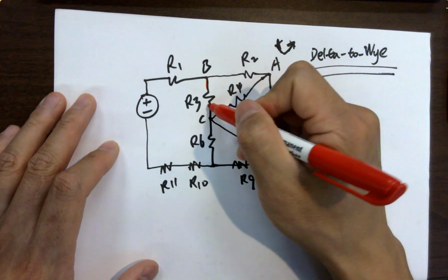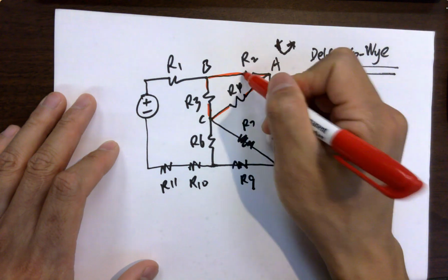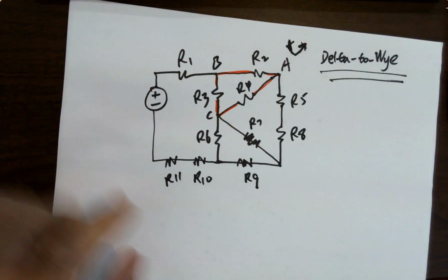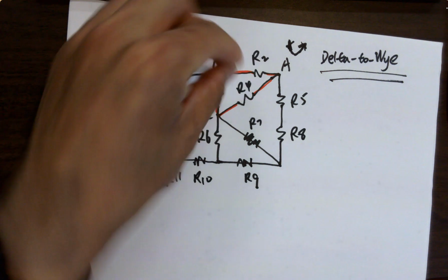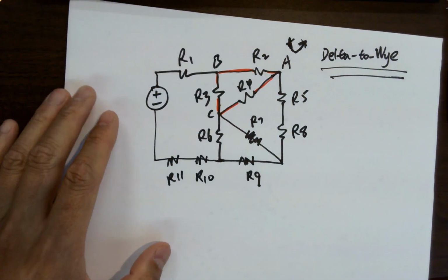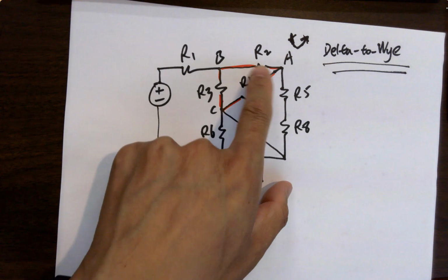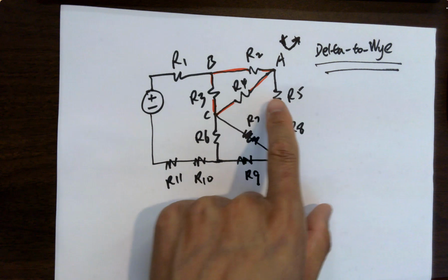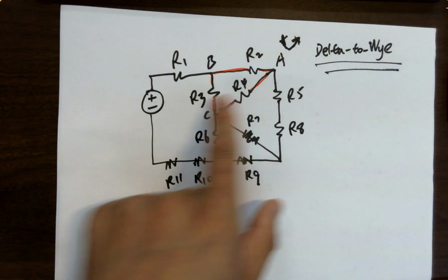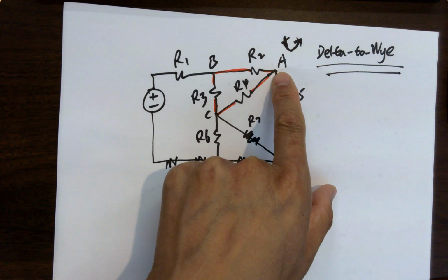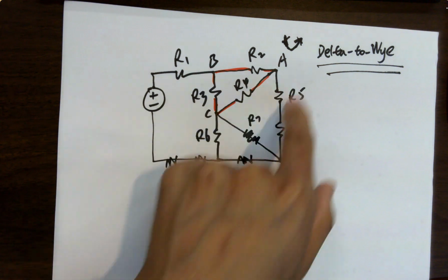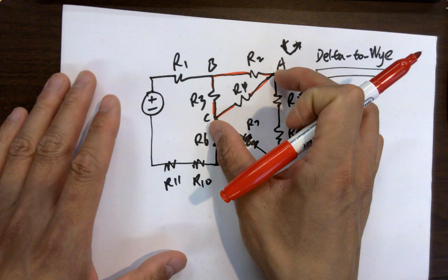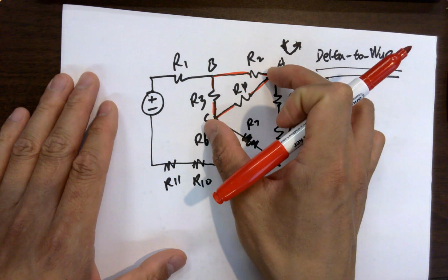Why do we have to convert it? Because it's just trying to simplify it. It's easier to find the parallel resistance. Right now it's getting all the in parallel, sometimes in series, it's difficult to solve. So we're going to convert this triangle into a T-shape to simplify it. The first thing you want to do is label it counterclockwise. Start from a point, for example here, A, B, C, counterclockwise. And then because you are using this one as AC, you always start from the side called AC.